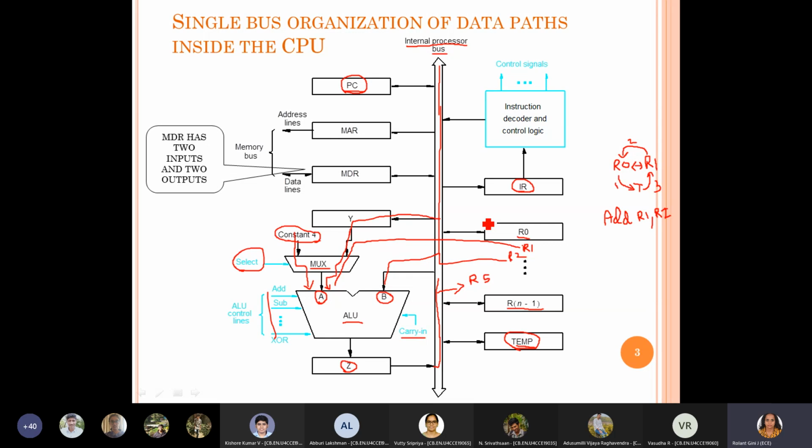So we go for an additional storage unit, which is the memory here. All the program and data are stored in the memory, and we access the memory and get the data whenever we require. For that, the operation will always be through registers only. From the processor and controller, whatever data is required, or any data you want to store in the memory, the access to the memory is only through the memory address register and memory data register. MAR stands for memory address register and MDR stands for memory data register.